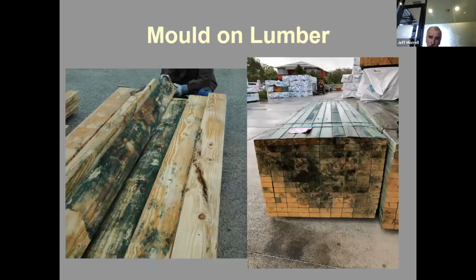They can grow on timber, as this lumber pack has lots of mold on it. This one is a bit of an allergen, and that's probably why we worry more about mold. Mold is a sign that the wood has been wet for too long. If you have mold, that's a problem, but it isn't going to weaken the wood structurally.